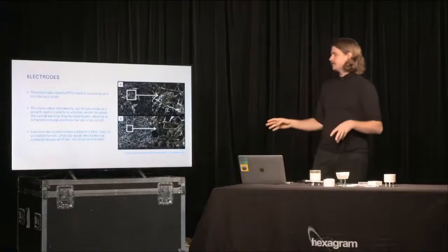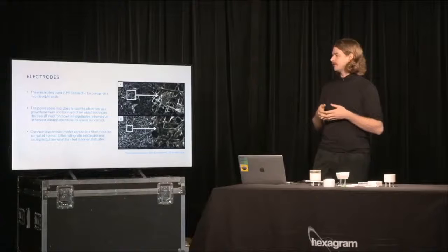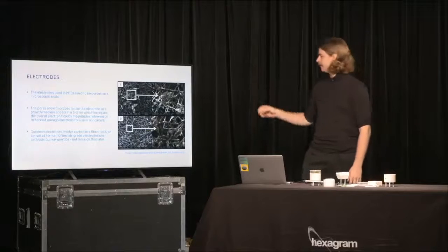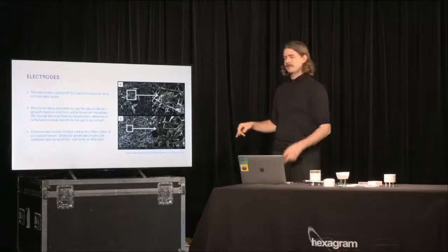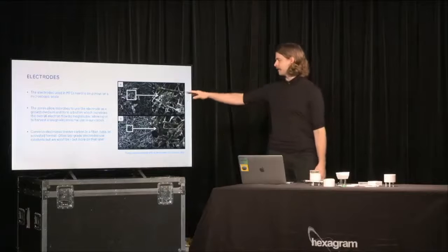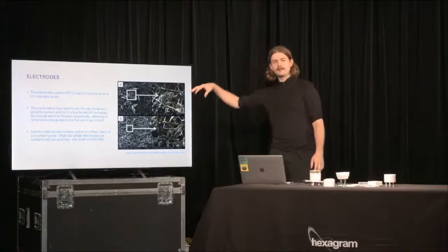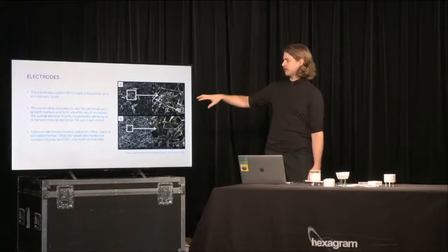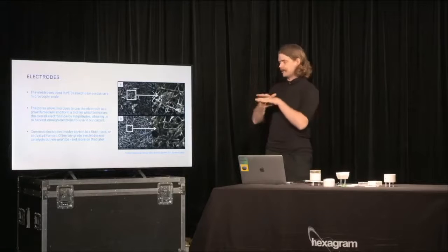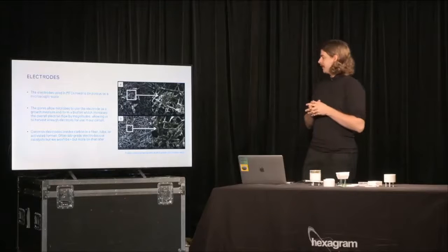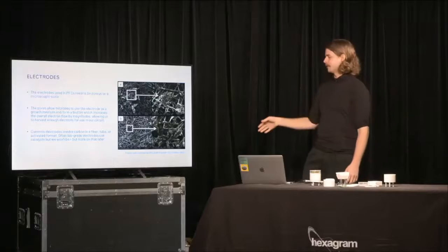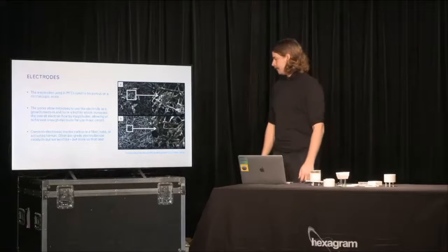So the electrodes, usually electrodes are pieces of metal, but here we're going to be working primarily with carbon. The reason we use carbon is because it's very porous and it gives the bacteria a place to grow, like all of these threads. So they form biofilms in the threads, which have a much, much greater surface area because we have all of these tiny threads instead of one plate. And the reason we need this is because the ions we're pulling are much less than you would get from a chemical battery.